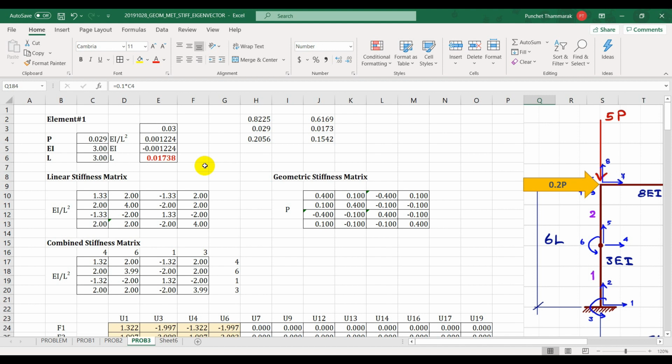The higher the lateral load, the worse the buckling load you will get. The curve will be pretty much like this, whereas the sharp curve will be obtained when your horizontal load magnitude is kept small. So it will behave pretty much like the structure without the horizontal load. So it is pretty much like the Eigen buckling case. Okay. So the lowest one is 0.2 p.